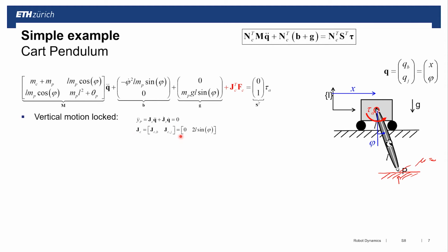So we calculated this contact Jacobian for that blocking. And this contact Jacobian is the contact Jacobian that also goes here into the dynamics equations of motion with the corresponding contact force. So if I want to calculate now for a desired motion, what is my tau? I can't, because I have my force and my acceleration in here. That's why we had to project this first. We looked at kinematics.